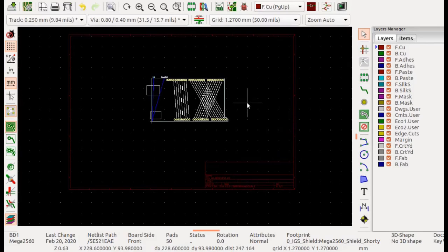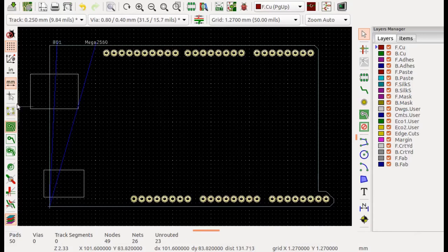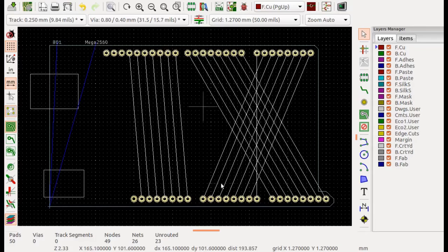Now I'm going to press the home key. We have the printed circuit board with all our wires being shown. These are called netlists, and these do come in diagonally. It doesn't come in the way we drew them up. Over here, there's hide netlist, hide board rat's nest. If you click on this button over on the left side, you can hide the rat's nest, and if you show board's rat's nest, it shows all the connections that you're going to be making.